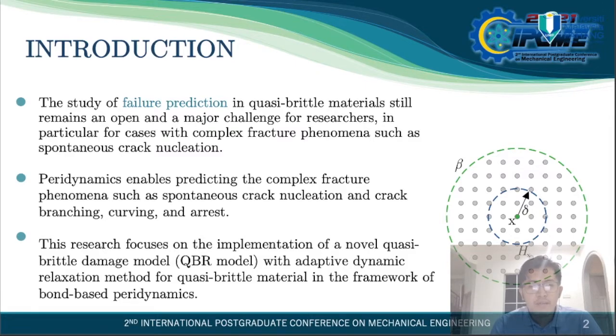So the figure on my right side of the slide shows that every point in the material denotes the location of a material particle in a body that is represented by the symbol beta, and these infinitely many material points, or particles, constitute the continuum. An infinite number of interactions may exist between the material point at location X and other material points. However, the influence of the material points interacting with X is assumed to vanish beyond something that we call the horizon. In this figure, we denote it by capital HX.